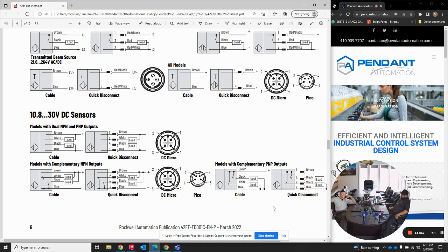So if you're troubleshooting third-party equipment like extendable conveyors, there have been some times where we've run into that. At Macy's, that's the first one. We wired it up and it didn't work, and we came to find out that the signals in there were NPN. And so we had to put in an interposing relay to swap the signal from NPN to PNP because our cards could only handle one or the other, however they were wired up.